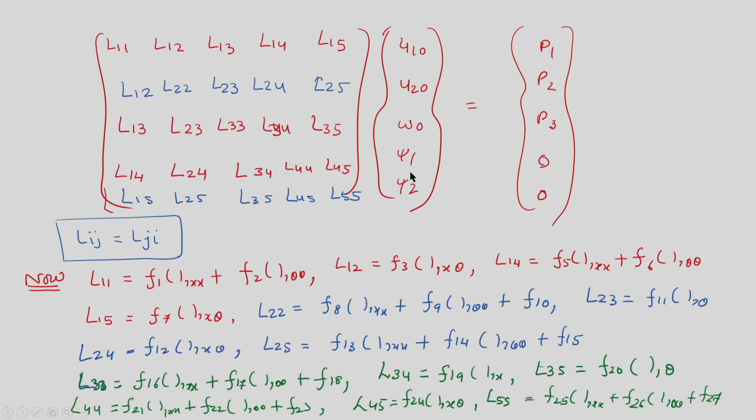So, ultimately, first equation, second, third, fourth, fifth. If we substitute all the values of M x theta, N x theta, Q x, Q theta in the main 5 partial differential equations, that leads to this set of equations, L u is equal to p, where L is a differential operator, a 5 by 5 matrix: L11, L12, L13, L14.